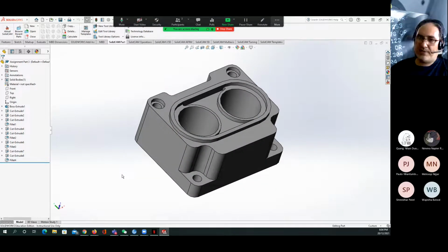The actual carburetor is made from casting of aluminum, but because I don't have the casting facility, I decided to machine the part. Especially because in the carburetor there are no pressures, and this is the simple version. We used to have something here to have the flip, and the flip we call the throttle. Every time we open the throttle, we allow more air to come.